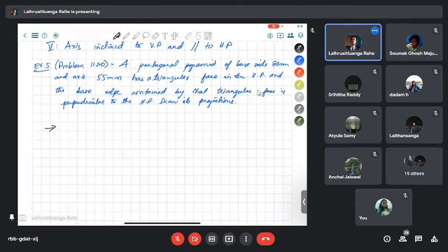Okay. So now, in order to do this, we are going to orient our pyramid in such a way that it is, in the first go, perpendicular to the vertical plane. The axis is perpendicular to the vertical plane, and we are going to flip it in such a way that one of the triangular faces is touching the vertical plane, is resting on the vertical plane. Okay, so in order to orient ourselves,